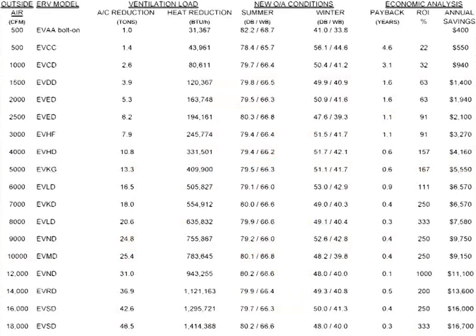We use this in the Midwest as a kind of cheat sheet, as an initial starting point, and then we'll calculate examples specifically when real projects come up. But this particular cheat sheet is assuming that in the wintertime I have minus 10 degree outside air on a design day, and it's assuming 95, 76 for my summer design conditions. And it's assuming 10 cents a kilowatt hour and $1 a therm in this particular example. We can obviously do it based on whatever utility price we really have.